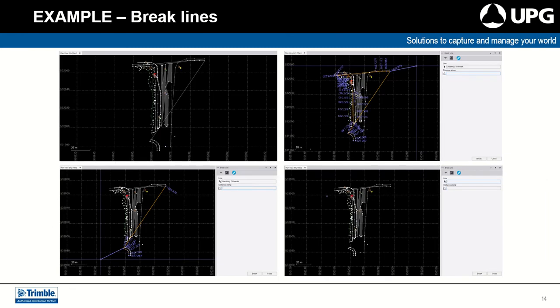In this example here, we've imported some data and we're going to look at the line that's crossing through the middle of our job. In this case, we've gone and opened the CAD commands and we've gone and used the break tool to break the line in the top right corner and the bottom left corner, and then deleted that line out. Now remember, if we reprocess these feature codes, then you would need to redo this line edit. If you went into the points tab and point spreadsheet and you edited the point so that the string at the top is a different string to the string at the bottom, this would have been addressed so that if you have to reprocess the data for any reason, that's not going to happen moving forward.